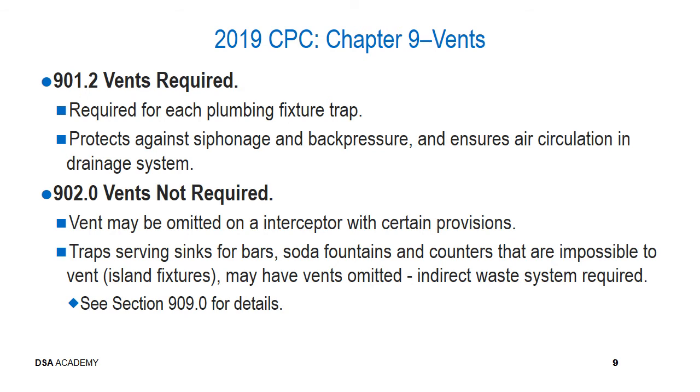And of course, the reason for these traps is that the water seal located inside the trap makes sure that no noxious flammable gases are able to translate back through the sewer piping into the occupied areas of a dwelling.